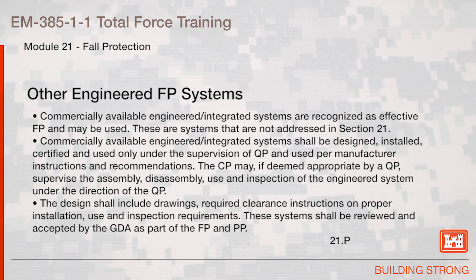Commercially available engineered integrated systems shall be designed, installed, certified, and used only under the supervision of qualified personnel and used per the manufacturer instructions and recommendations. The competent person may, if deemed appropriate by the qualified person, supervise the assembly, disassembly, use, and inspection of the engineered system under the direction of a qualified person.